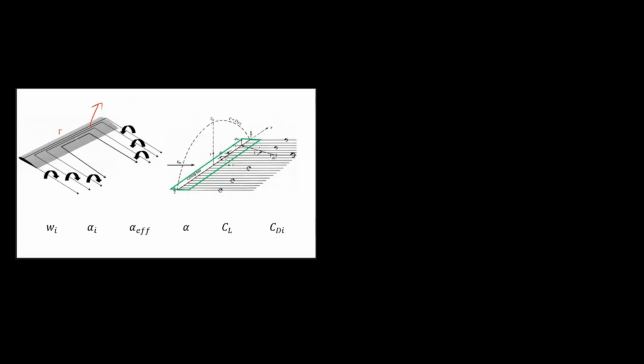So he wanted to derive the expression for the forces acting on the lift. He simplified this configuration. He placed all these vortex filaments in the same line. See, he coincided all of this. Here it is spreading over the wing, right? All those vortex filaments. But for the simplification of the theory, he coincided all these vortex filaments in a single line, that is the Prandtl line. And this line is called the lifting line.